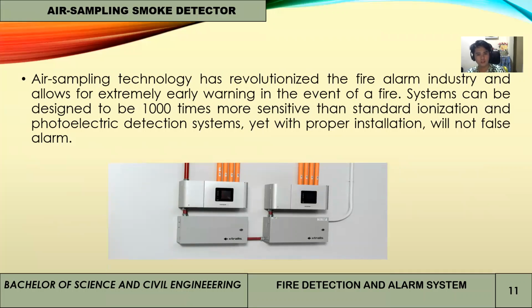Air sampling technology has revolutionized the fire alarm industry, allowing for extremely early warning in the event of a fire. The system is designed to be 1,000 times more sensitive than standard ionization and photoelectric detection systems, yet the proper system will not false alarm.